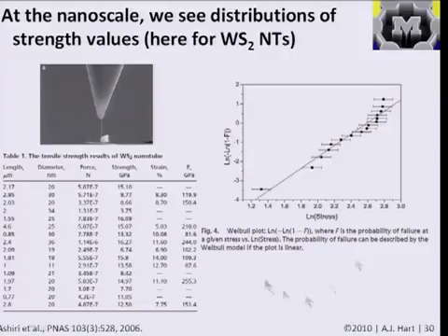And formally this plot is what's called a Weibull plot. Perhaps from undergraduate mechanics you remember Weibull statistics, and they fit the Weibull relationship, which is a line when you plot the axes between F and stress like so, and see that it's a pretty good representation. And also from the raw data here, you can see that there's a pretty big range in the strengths of the wires. It may depend to some extent on size, but for example here, you have a 36 nanometer diameter wire that has a strength of 16 GPa and a 30 nanometer diameter wire that's like 10 GPa. That's a 60% difference. That's a pretty big difference. That's more than we might see exists for a macroscopic material.